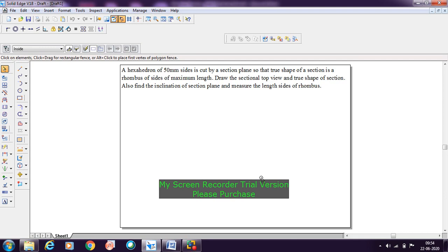Now instead of giving it as a cube, it is mentioned as the hexahedron. So after coming to know that it's a cube of 50 mm sides, all the sides are the same, the length is equal to breadth, which is equal to height. So in this case, it is mentioned only as 50 mm. Here also it is a hint: if only one dimension is given for the solid, then it is the cube. Now in this case, the length is equal to 50, the width is equal to 50, and the height is also equal to 50.